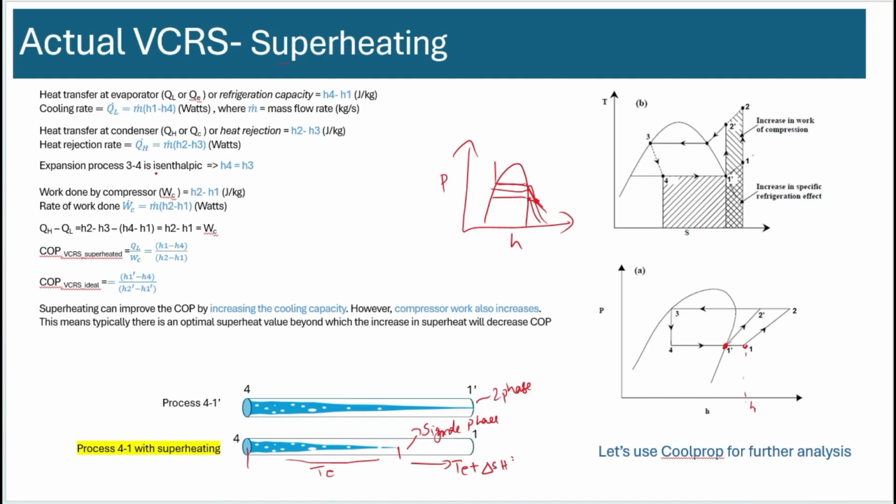Okay. So what happens is if you try to calculate the COP of the superheated condition, QL over W_HC, you basically have H1 to H4 in terms of cooling effect. Assuming that the heating in the evaporator is used for cooling your system, or cooling whatever you're trying to cool, then you could use the whole left to right here as the cooling load.